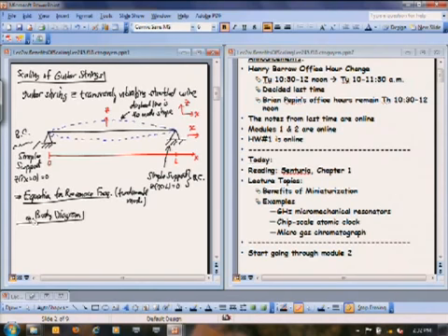And so we kind of already have a picture for this. In making a free body diagram, what I'm really trying to do is write down a condition for the dynamic equilibrium of this moving, vibrating string. So I don't want to work with the whole string at first. What I want to do is grab a small piece of it. And that small piece is going to give me all the different physical constraints that define a differential equation that will then determine for me what the frequency is for this.